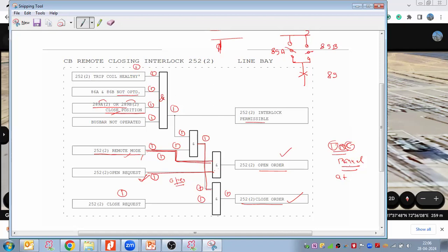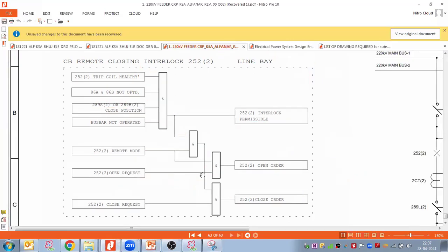See, we are operating the equipment, Rahul, through this interlock. Through the operations of the equipment, we are discussing all these things. If any fault happens, the relay will issue the tripping command to the circuit breaker in service. And suppose you wanted to do any local testing, you have a TNC switch at the breaker, and you can do the testing by using that switch. So this is what we are discussing: how the equipment would normally be operated through the BCU.